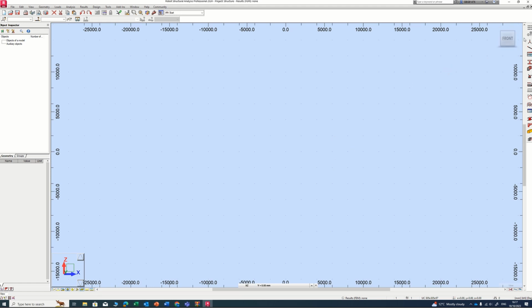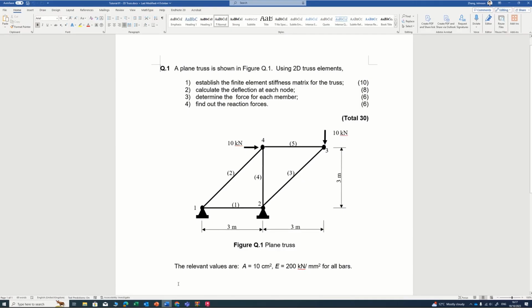After that, we need to create the grid. We have a grid line here and another grid line here. In the Y direction, we only have one repeat. For the X direction, we have one here, just first repeat and second repeat, and between the repeats the distance is 3 meters.